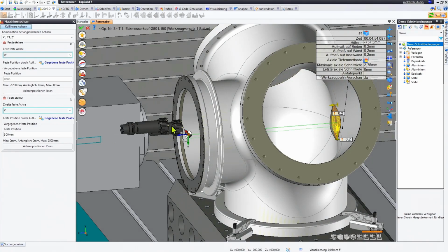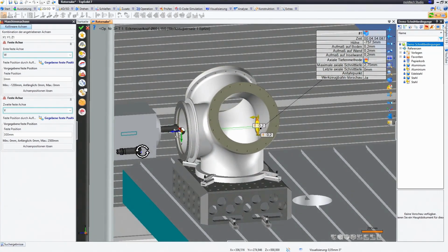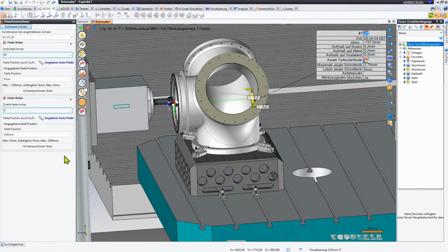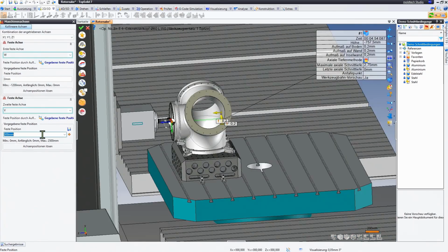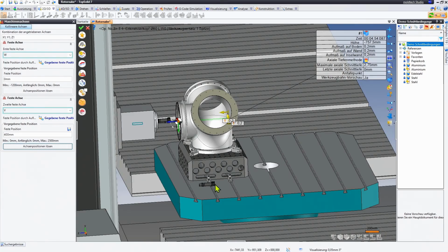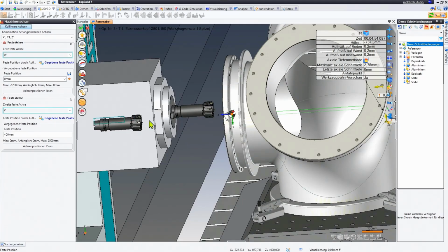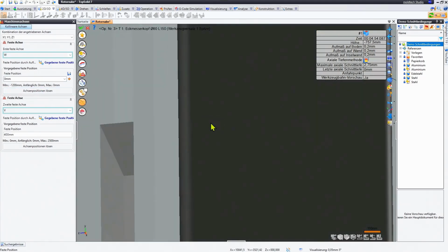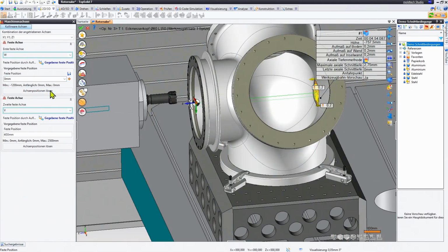And here too, I can now go to the collinear axis and say, the table can stay at 300 millimeters, and I could theoretically enter 400 millimeters as well, and immediately see what happens here. The table moves a bit backward. But I could also say that I want the quill to extend out here in the very middle now, because I truly want to work with the quill in this particular area. But the controlled axis is still the Z1 axis.